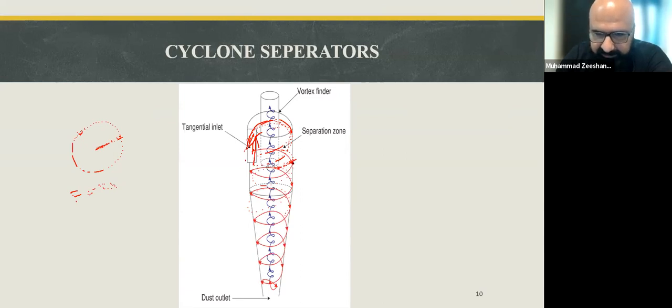And in fluid dynamics, we study that the velocity of the fluid on the wall is low, is zero, right? Boundary layer. That's what we call the boundary layer. So when the particulate matter reaches the wall, over there the velocity of the fluid is low with low turbulence, and ultimately the particle falls down due to gravity near the wall, and the PM is collected at the bottom, while the comparatively cleaner gas moves upward and is collected at the top, right?